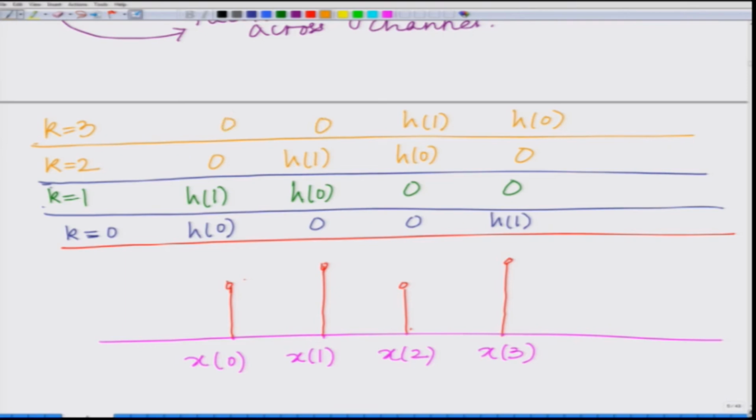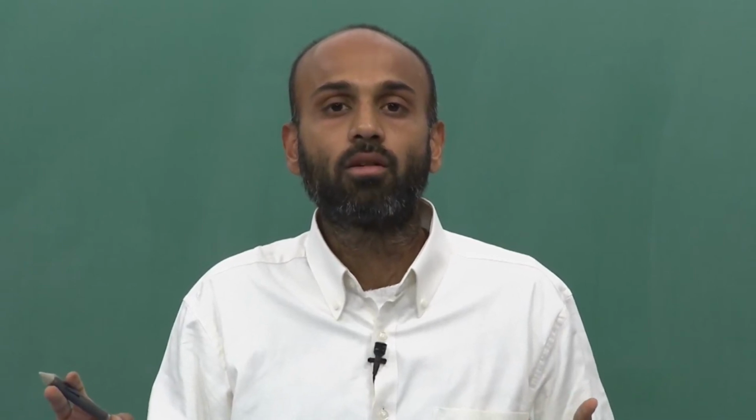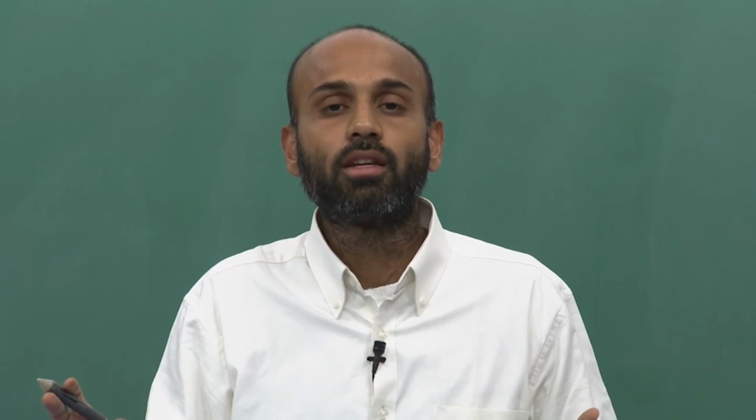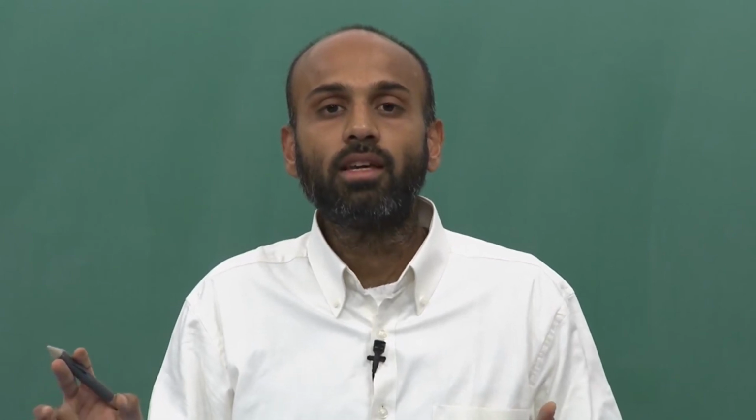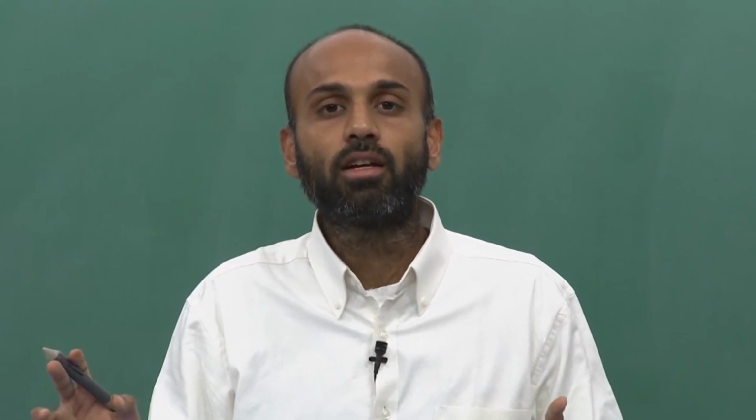And now, as you can see, if you observe this figure closely, I have the symbols x0, x1, x2, x3, and the channel taps, or the channel filter, H0, H1. You can see that the channel filter is rotating over the transmitted symbol.